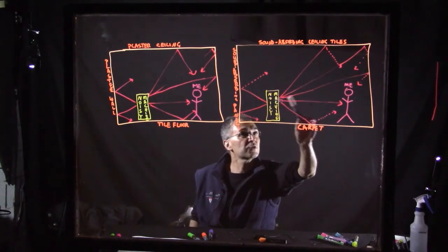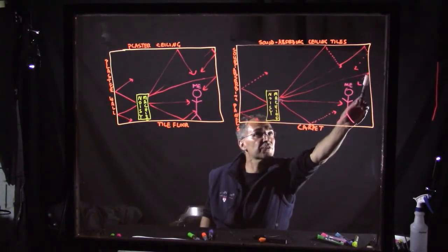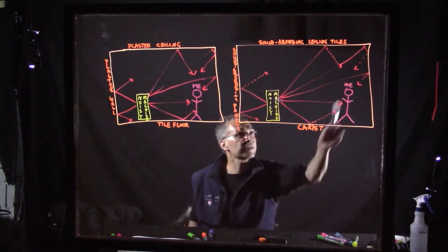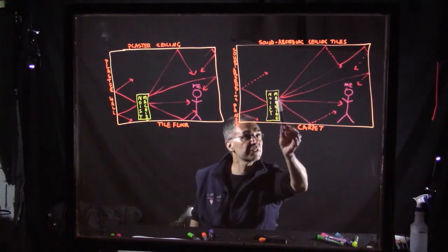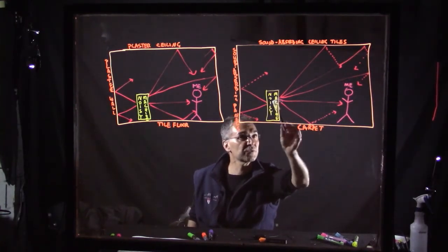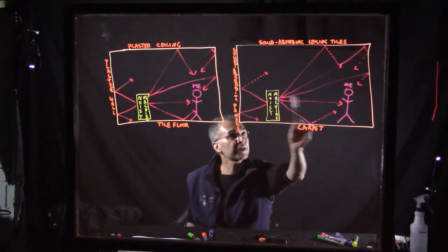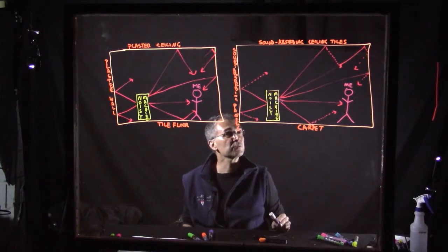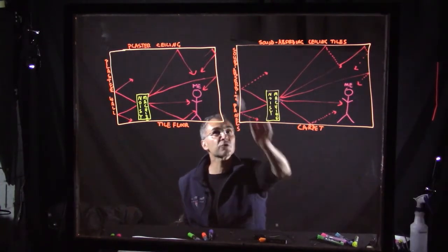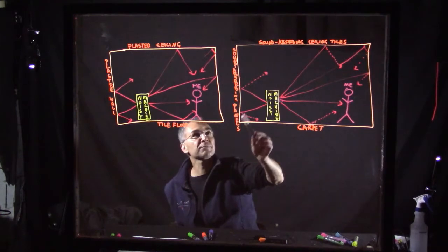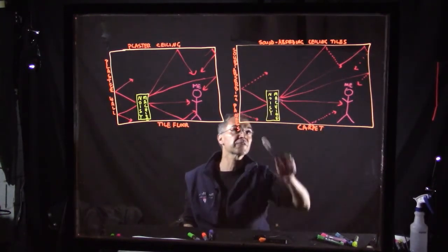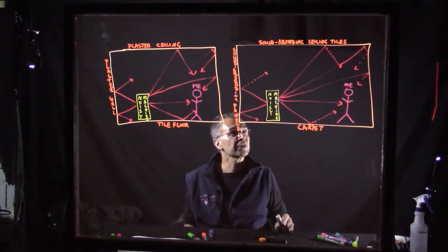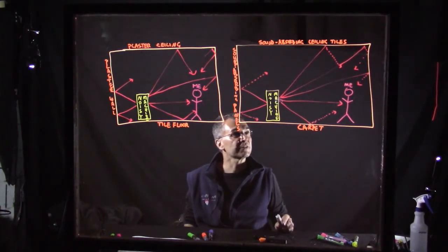And over here, here's a ray that hits the wall behind me, but again, when it reflects, it has a much lower energy level. So the direct ray still reaches me with the same sound intensity, but all of the rays that reflect off of these properly treated surfaces, the carpeted floor, the wall with the sound absorbing panels, the ceiling with the sound absorbing ceiling tiles, every time one of these rays reflects from one of those surfaces, it's significantly attenuated.